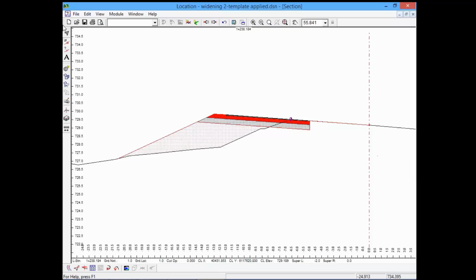And the other thing that's really valuable is you can just hover, and it'll tell you what material you're filling and what the cross-sectionals are. So kind of nice for debugging your templates, because they can go wrong. I don't have a bad example to show you, but believe me, they can go wrong. Sometimes you'll see the hatches overlap, which means you're getting double counting. Or you'll see a piece of missing hatch, which means there's no volume being counted.